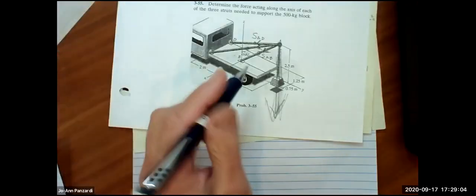Joanne, I have a question about that setup. David, if you look back at the picture, at point A, I don't see anything going in the positive Y, right? Correct. Its weight goes negative Z, down, right, but nothing is going in positive Y. So that looks like another example where it's going to be unbalanced. You're going to have a bunch of stuff pushing into point A, right, but what's going to balance that?